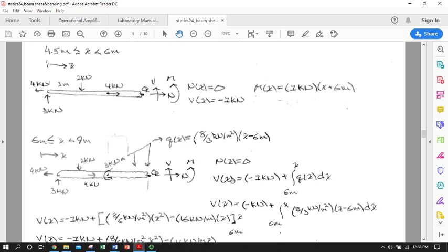If we want to get shear force at our cut section anywhere there, we're going to end up using our shear force from the previous section plus the contribution just to the distributed load. So we have our -1 kilonewtons coming up from the previous section, plus what V has to be to balance the distributed load just within this section.